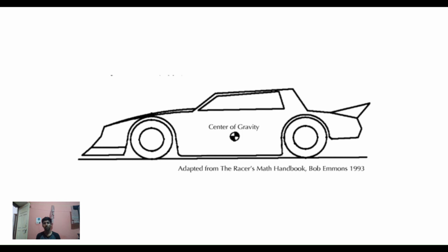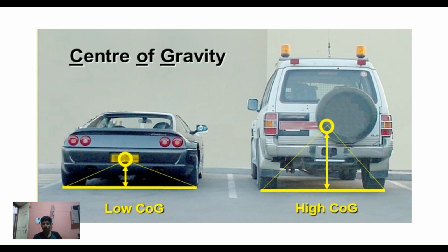So again, it's a matter of finding the sweet spot. Lower the CG as much as you can, but not while sacrificing your suspension abilities too much. Maintain enough suspension bounds so that all the obstacles or all the cornering actions can be done more easily. I was telling you all these.